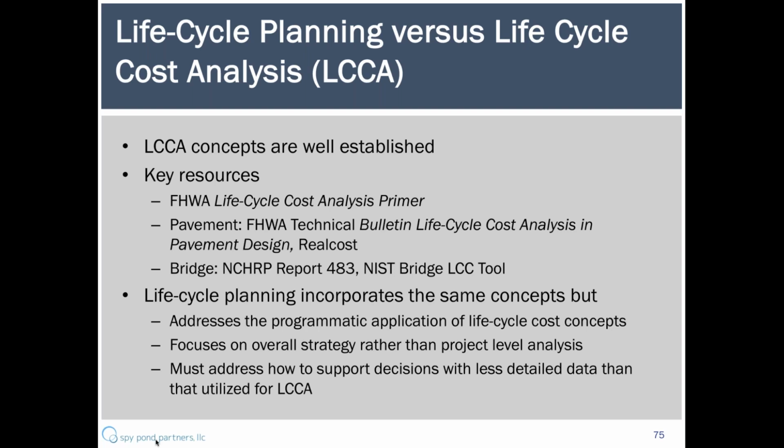On the bridge side, there's not as much out there, but the authoritative report is NCHRP report 483 on bridge lifecycle costs. Hugh Hawk wrote it. It's a great report to read on this topic. And the National Institute of Standards and Technology has a bridge lifecycle cost analysis tool for use in bridge design. It's also a good resource. So there's a lot of stuff out there already for lifecycle costs.